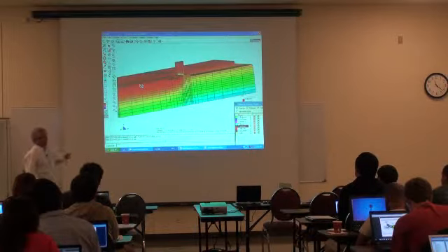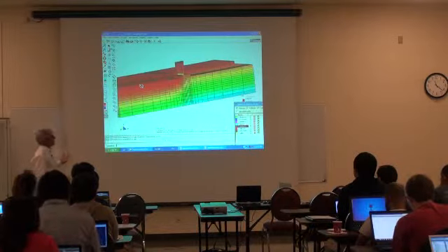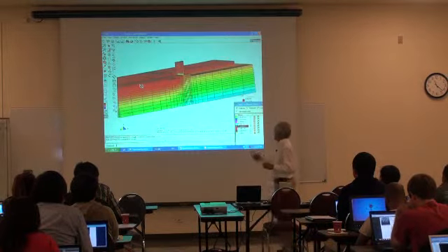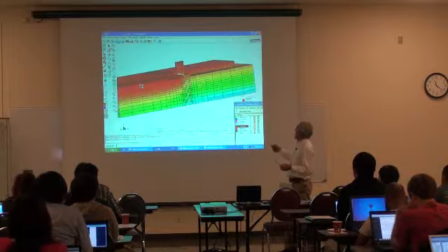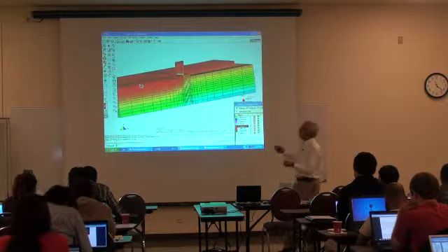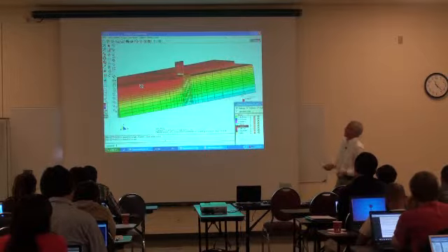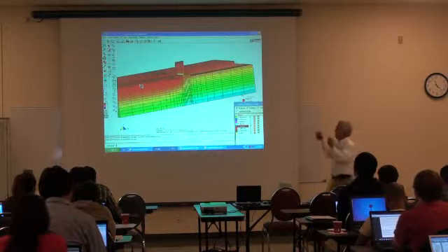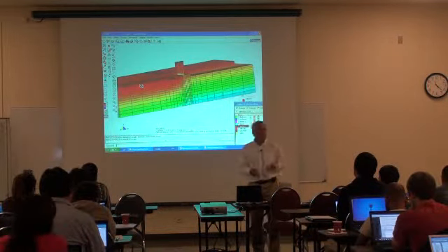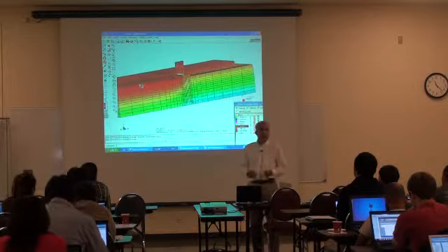We have to deal with those things and try to reproduce as well as we can the initial conditions, so that once we have them, we can apply the lateral loads and go from there. Once we have a model that works at this level of coarseness, our plan is to go with a more refined model. Now this is running in 1 day, and we can wait maybe 3 or 4 days to get results. But at least you start with a coarse mesh, and then go into a more refined one. That's all I wanted to show today. If you have questions, please let me know.